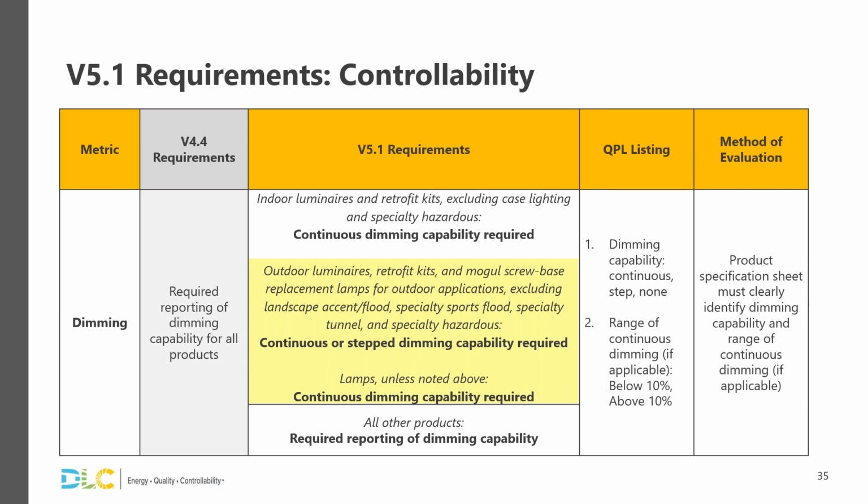So if you're familiar with this product category, the Mogul screw base HID replacement lamps can be associated with indoor applications like a high bay or outdoor application. And so those products that are qualified in the outdoor PUDs and any of the outdoor luminaires and retrofit kits must be capable of achieving continuous or stepped dimming. Now, stepped dimming is unique here to outdoor, and it is defined in the policy document, so you can take a look at that if you have questions about it.